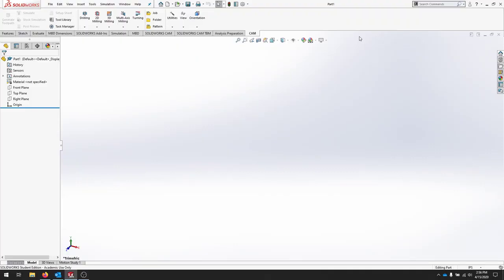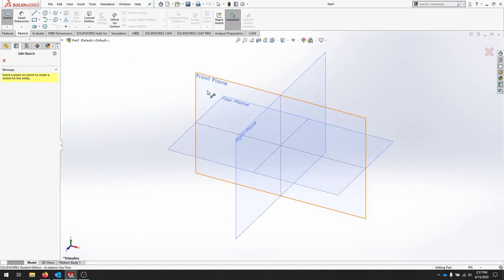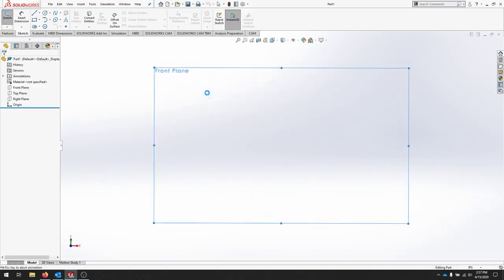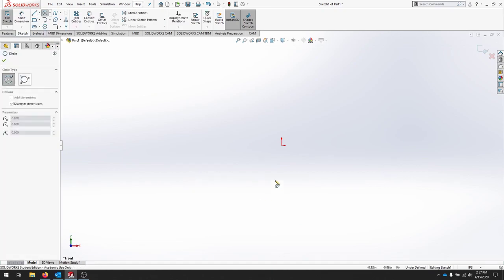We're going to be looking at some advanced 3D modeling and construction tools in Solidworks, and we're going to be creating a hairdryer assembly. So to get started, we'll create a new sketch. We're in inches right now, so I'm going to create a new sketch on the XY or front plane. From here, we're going to draw a circle in the origin.